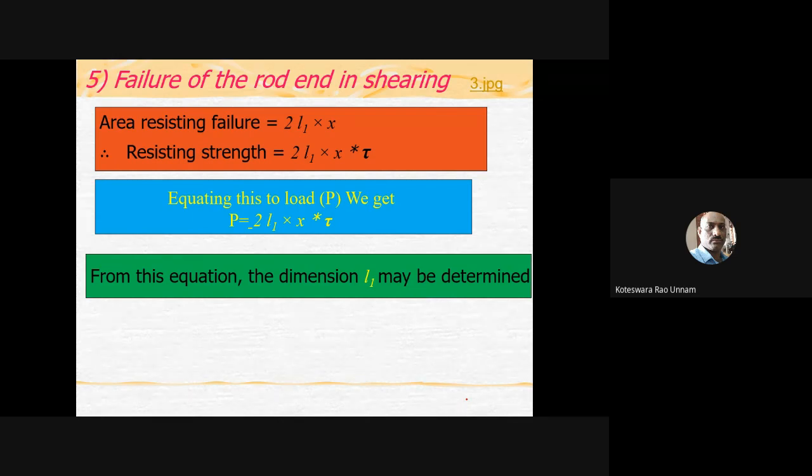In the second step, you have to calculate what B is. That is the mean width of the jib and cotter. Then after that, you need to use the empirical relations again to find the small b and small b1. Then the third step, what we did, is we calculated T1. T1 is nothing but the thickness of the strap. You can calculate it by considering the tensile failure across the slot for the strap. So you get T1. Then once you get T1, then L1 and L2.